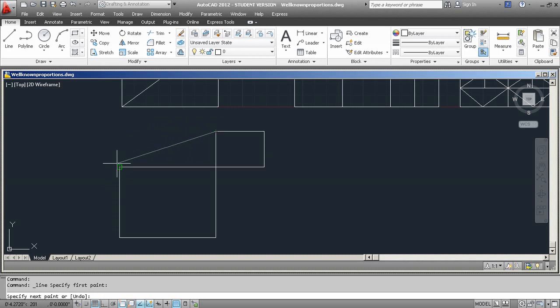Now we're going to create two rectangles, and form the two rectangles into one rectangle using the Object Snap Tracking feature. Object Snap Tracking sees the relationship between where you want to go and where you're coming from and shows the intersection. When you see the ghost line or footprint line, you need to show with your cursor where you want to go and where you want the footprint, and then press the enter key.